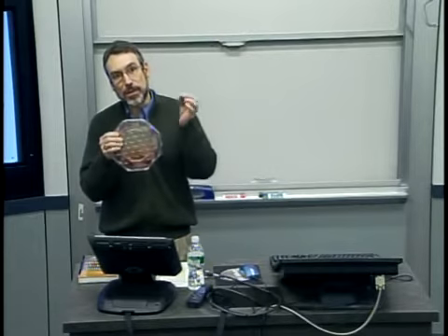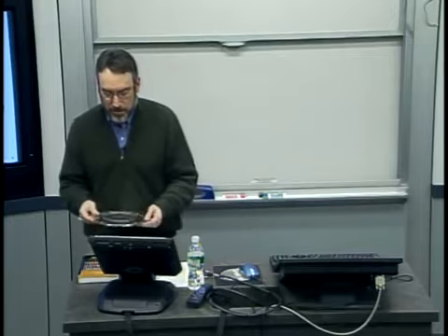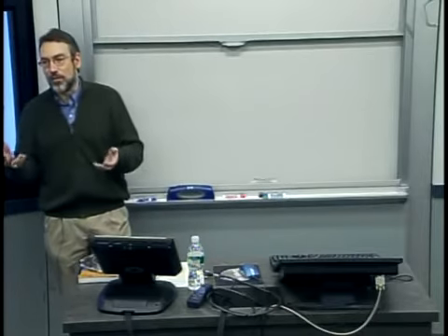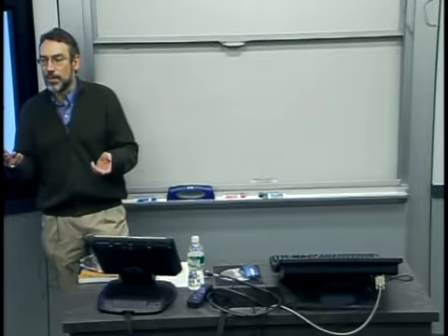And in fact, in older technologies, I had to make sure the whole wafer was lined up because I had a big glass plate that I was using in almost a 1-for-1 transformation. So everything across the whole wafer had to be lined up. And if the temperature of the glass plate and that of the wafer were off by a degree, the thermal expansion would upset the alignment, for example. So over time, you've seen both to achieve smaller dimension, but also to achieve better control, a number of that as the driver for the evolution of photolithographic equipment.